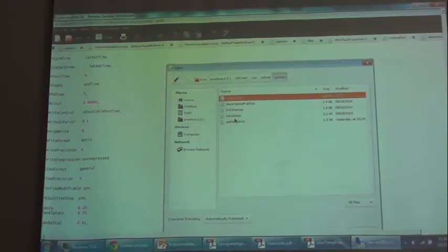Yeah, for this, how the number is calculated is based on the advection velocity. It's a nonlinear advection, right? So the advection velocity will be the same in all the transport equations. So it's U, because any quantity that is transported with the velocity. It's the same velocity that appears in the momentum equation as well as in the concentration equation.